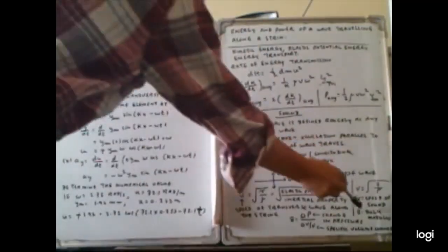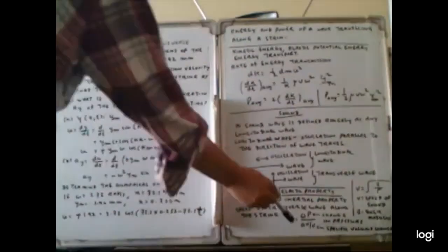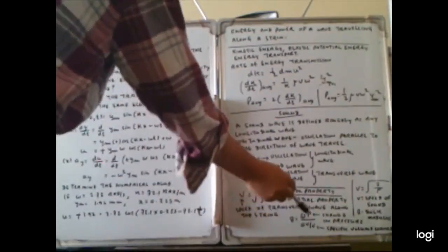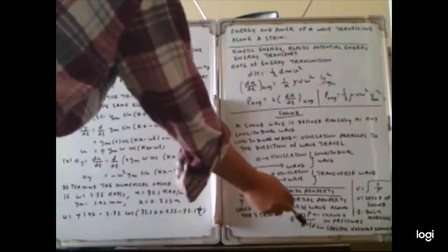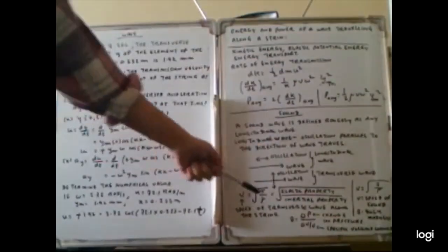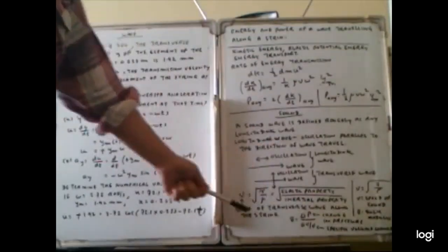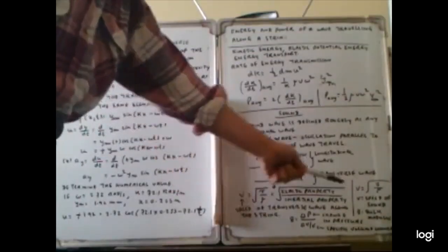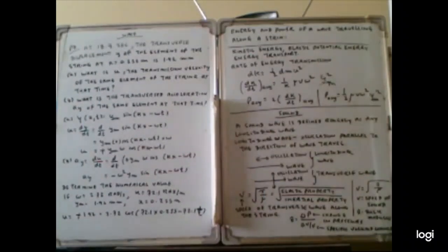In this case, v is the speed of the sound, and B is the bulk modulus. Bulk modulus can also be calculated as B equal to minus delta p by delta V by V. Delta p is the change of pressure, delta V by V is the fractional volume change. So sound velocity depends on the pressure of the medium, and those things affect the sound velocity.